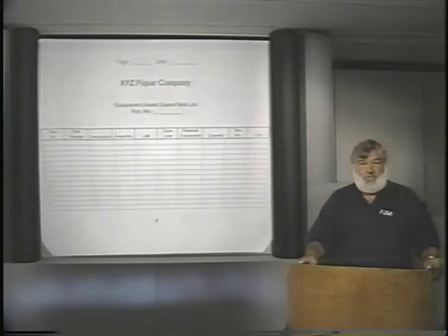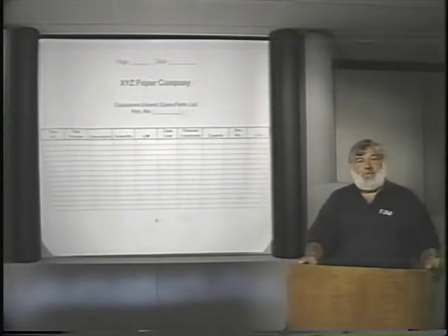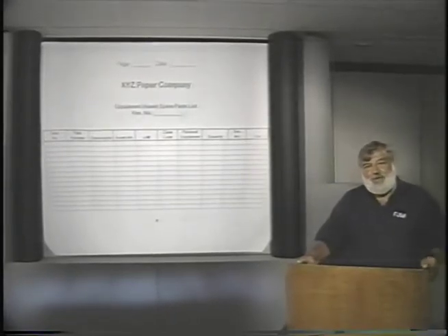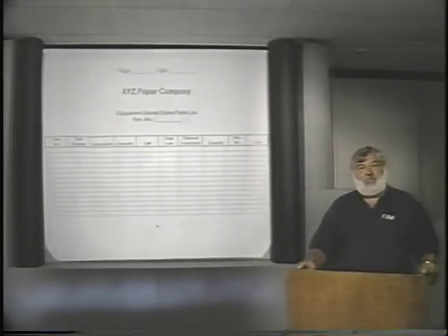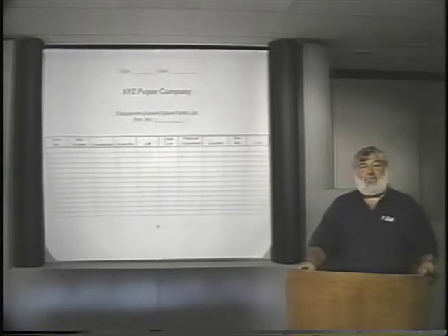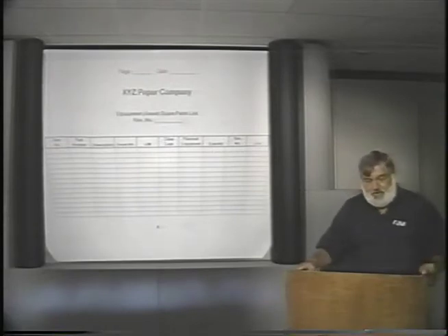Therefore, when an engineering change notice is processed for that spare part, we would want, on the engineering change notice, not only to have the spare part number and the asset that part number is going to be changed on, but also the page and the line number associated with that engineering change notice, so that we can make certain when we go from one revision to another for that spare part number, that all of the source documents are going to be updated accurately, and that's the reason for the item number.